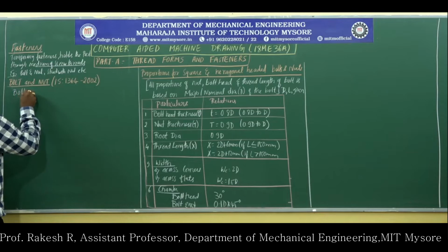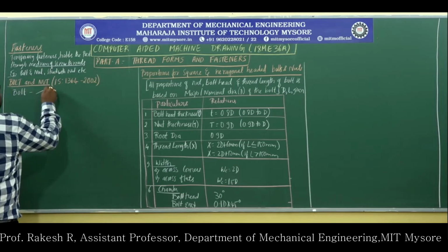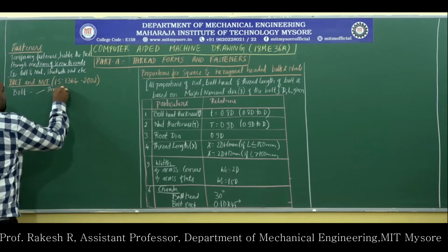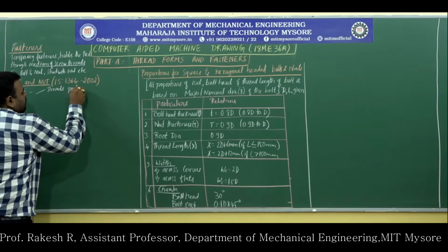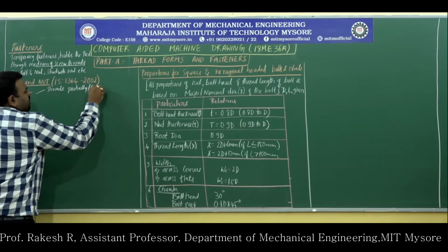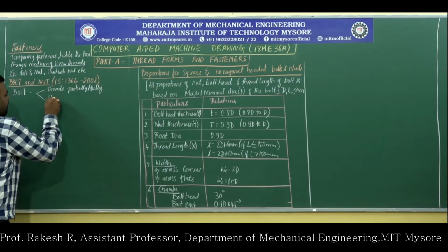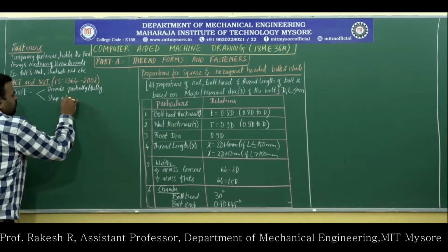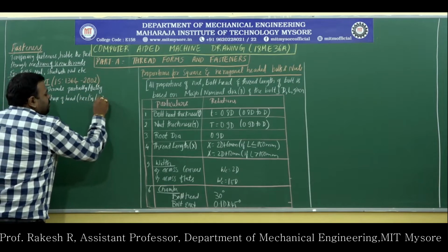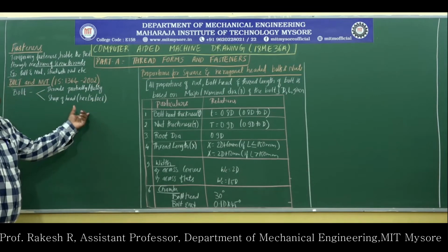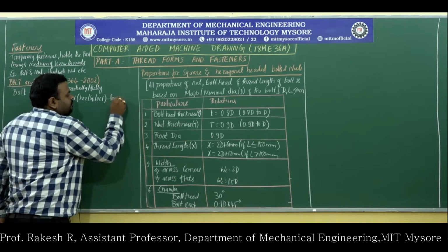A bolt is a solid cylinder which has threads partially or fully, as well as a shape of head, with hexagon, square or octagon, and this shape of head is obtained by the process of forging.